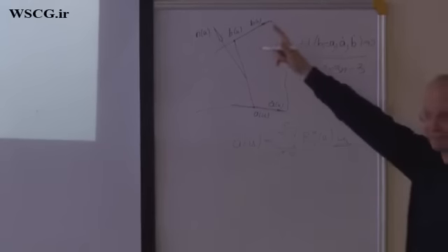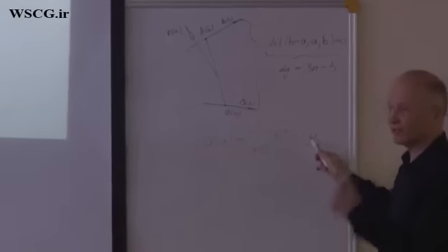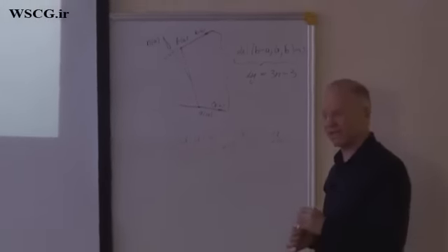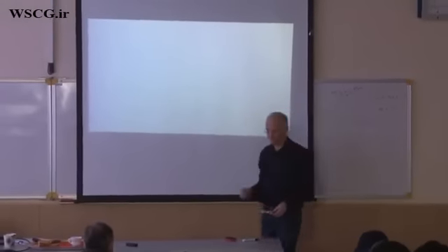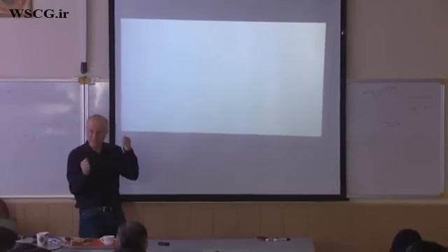So in my figure before, this was n equals 3. So you have control points a0, a1, a2, and a3. Right? A cubic polynomial has 4 coefficients here. And in the Bernstein form, and likewise with the b. So these are the control points. But as you see, you cannot fix all points and manipulate just one, because then you will for sure destroy the developability.